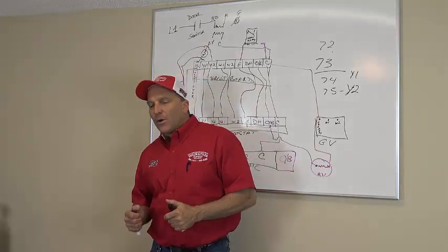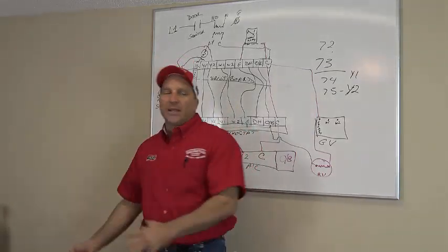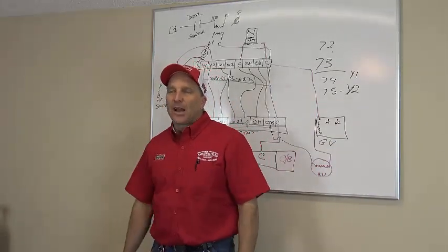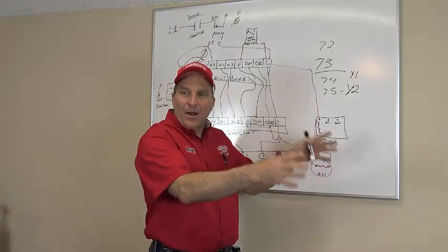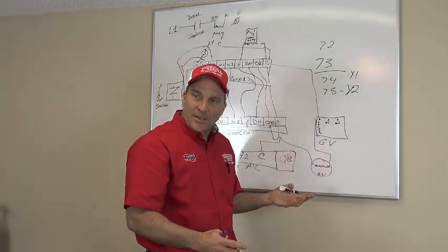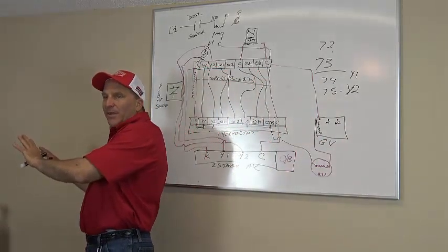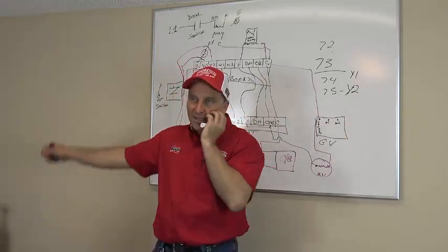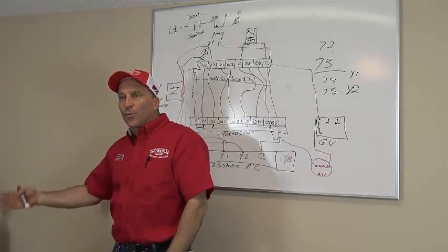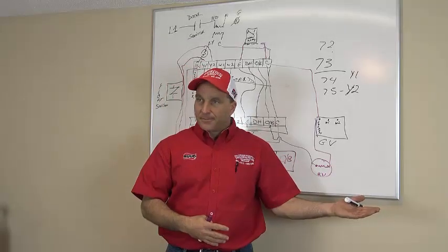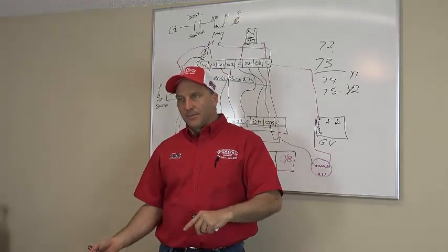If the temperature outside on a heat pump gets to 30 degrees, is there any more heat outside to bring inside? Because isn't that what a heat pump does? It takes the outside heat and brings it inside the house. What does an air conditioning system do, guys? It takes the heat inside and brings it outside, right? So a heat pump takes the heat outside and brings it inside. As your temperature outside drops down, is there any more heat left outside to bring inside? No. So your heat pump is no good anymore, is it? So now you have to have backup heat.